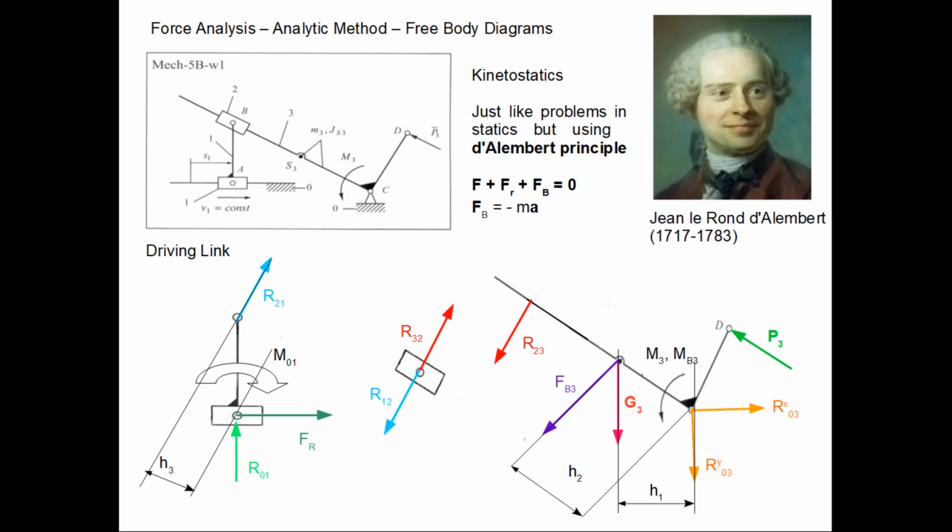This inertia force is not a real force, it's just, let's say, a mathematical convenience to change the dynamic problem into a static one. So if you introduce these inertia forces as equal to minus m times a, as well as the torques due to inertia equal to minus I times epsilon, then you can treat these as extra forces acting on the mechanism, and you can just analyze the static equilibrium of all of the forces.